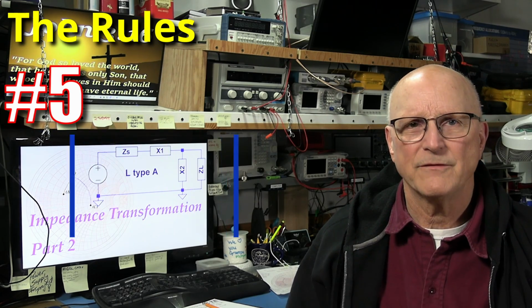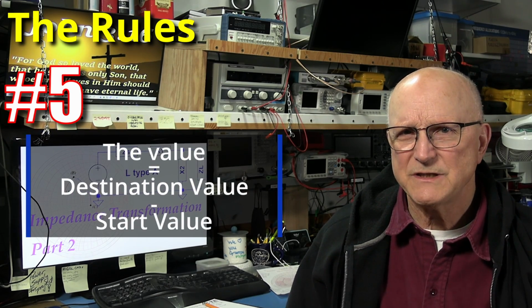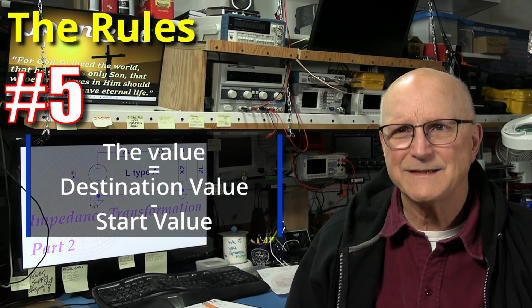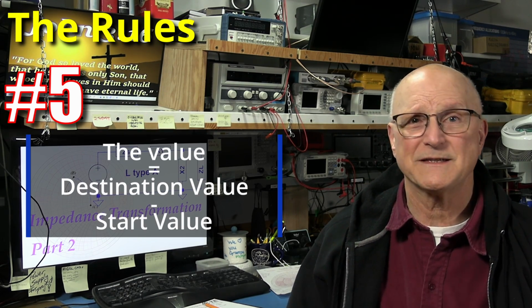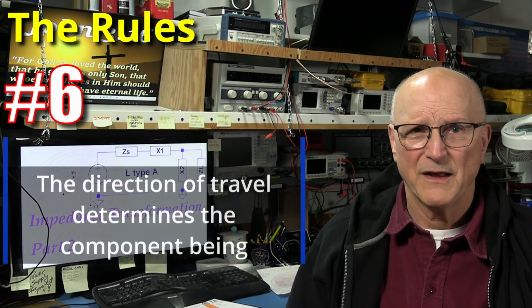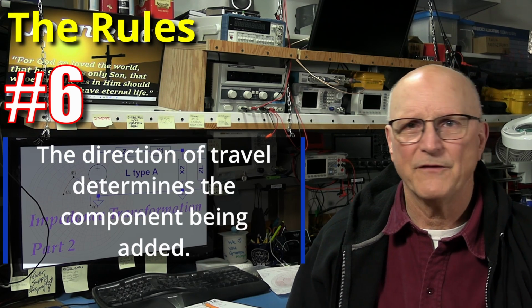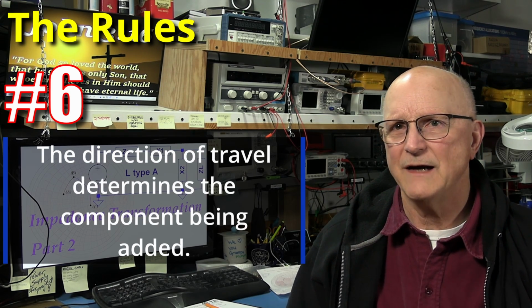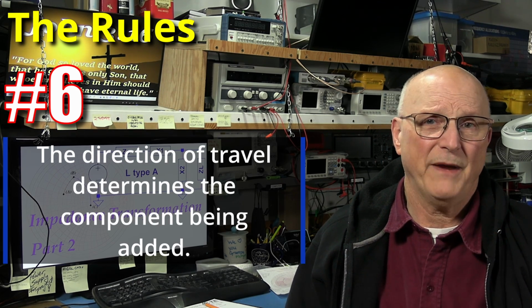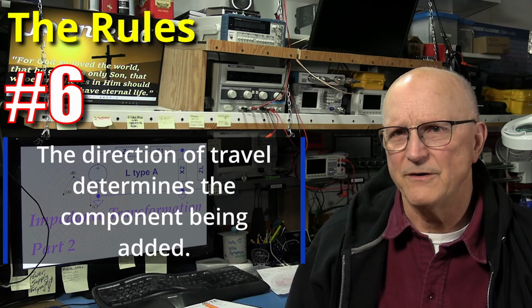Rule number 5. The value we're interested in is always the destination value minus the start value. The signs will kill you. Rule number 6. The direction of travel on the constant resistance and constant conductance circles determines whether you are adding a capacitor or an inductor.